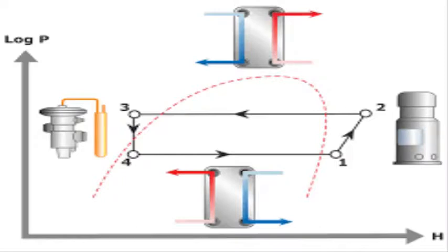Basic refrigeration cycle principles. Refrigerant in the latent state, or vapor refrigerant in the process of changing state to liquid, is the phase where it absorbs or ejects large quantities of heat. The quantities of heat absorbed or ejected can be managed by controlling the pressure and temperature of the refrigerant. The boiling point of a closed system liquid can be controlled by changing the vapor pressure above it. Gauge pressure is used to determine the pressure inside the closed refrigeration cycle system. It's expressed in pounds per square inch gauge (PSIG).